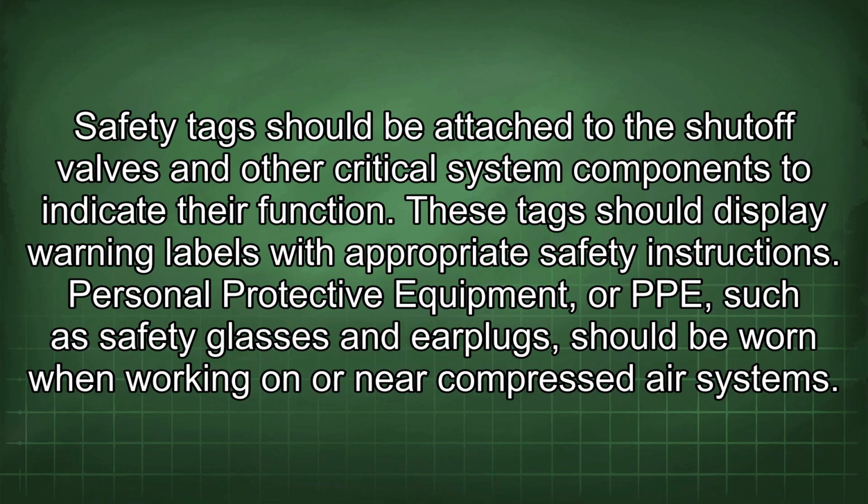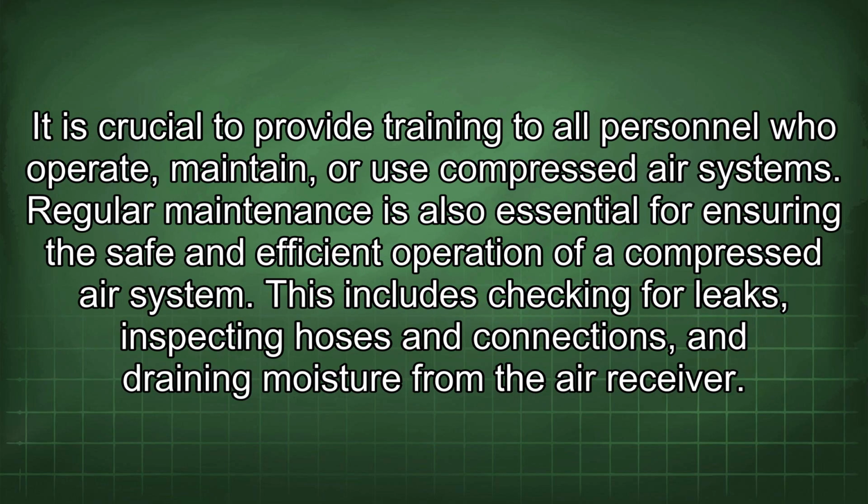Safety tags should be attached to the shut-off valves and other critical system components to indicate their function. These tags should display warning labels with appropriate safety instructions. Personal protective equipment, or PPE, such as safety glasses and earplugs, should be worn when working on or near compressed air systems. It is crucial to provide training to all personnel who operate, maintain, or use compressed air systems.